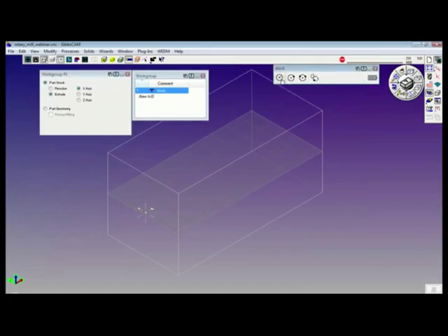circle with a center point and a radius, and in the absence of a center point, because typically I would pick a center point and create a circle based on the radius, and I don't have one, so I'm going to click on the CP tile. The CP tile stands for center point.